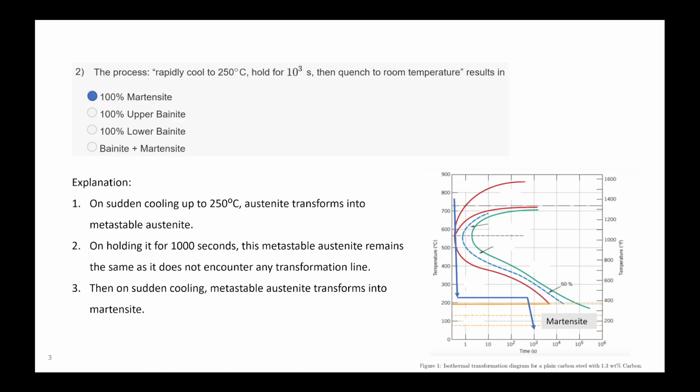So it won't be homogeneous after necking. That means the direction of deformation will be different, along different directions. Before that, it will be only along the tensile force direction. Your deformation will be equally spread in the entire gauge length before the formation of necking. After necking, it will be restricted. Your strain will be more in the localized region where your necking has occurred.